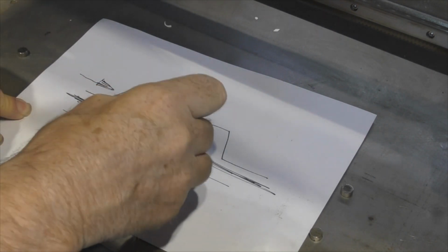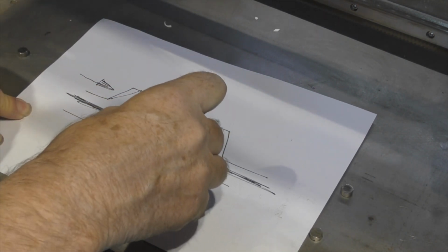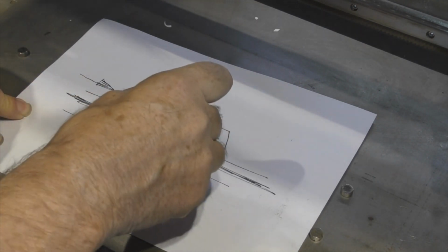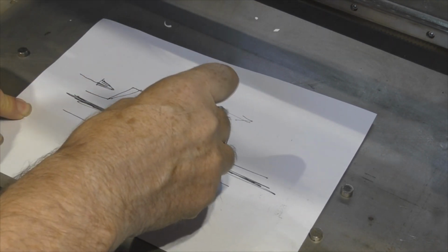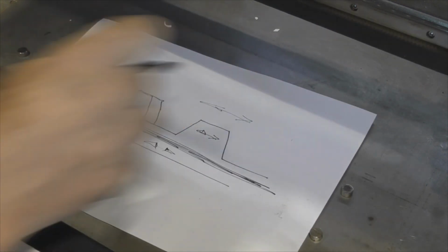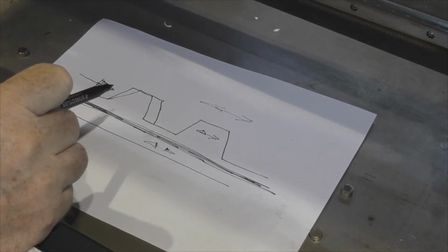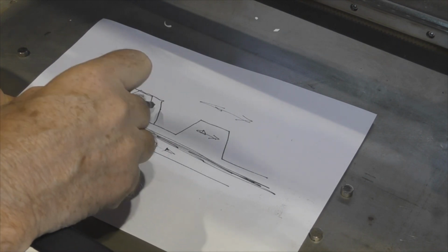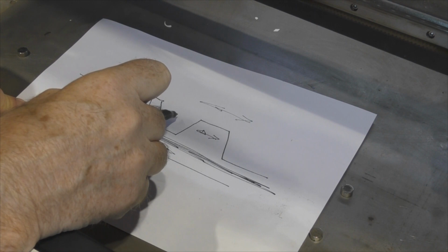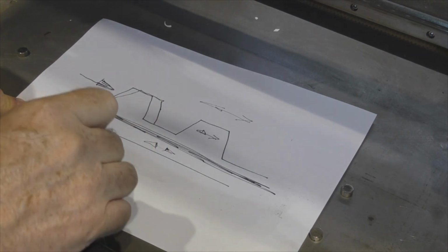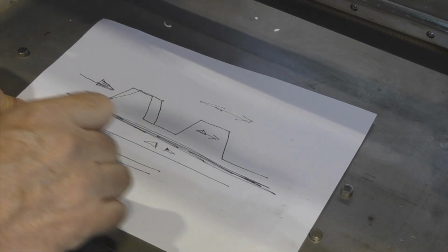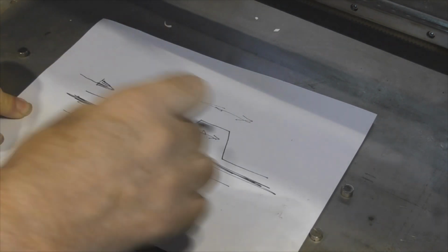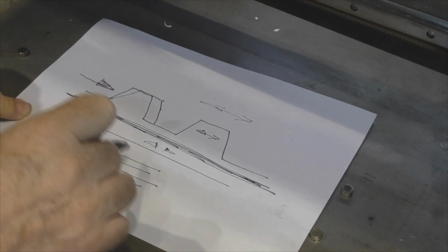In our particular instance, we've got oscillating motion in two forms. First of all, in the form of going in one direction and then the other with our scans. And so consequently, we've always got the risk of a small amount of backlash at the end of the stroke when we change direction. And that we've seen when we do a scan and we get scan lines that look like this. Now, that's the main reason why we're getting these scan line problems.